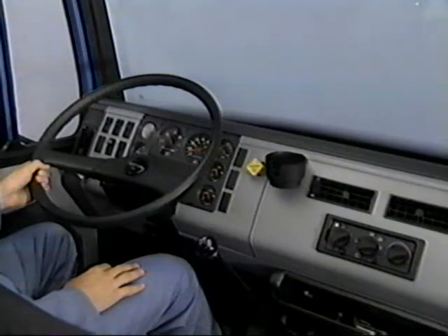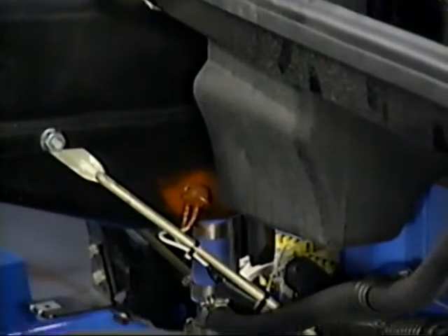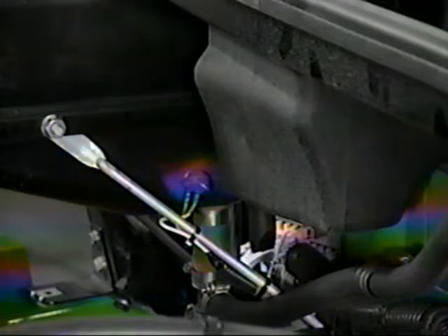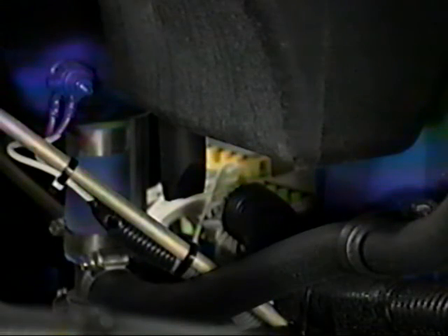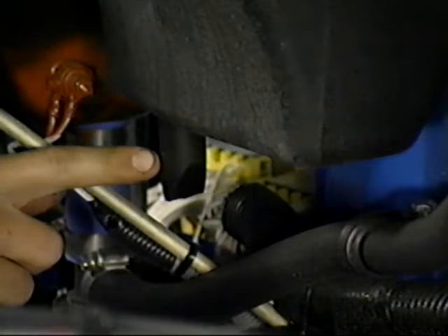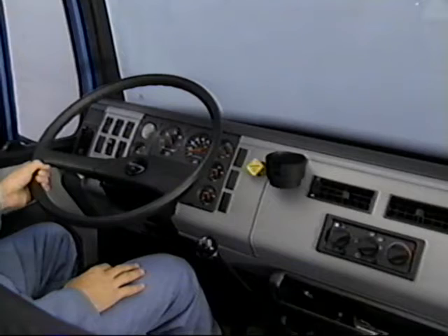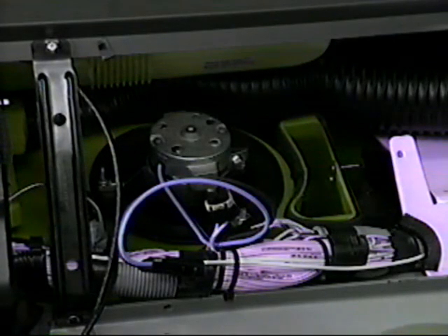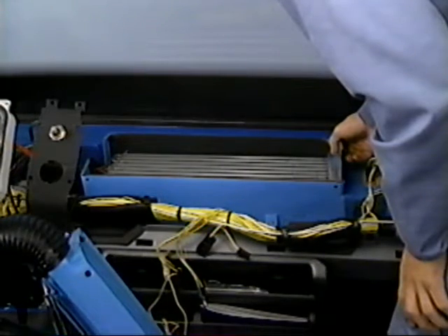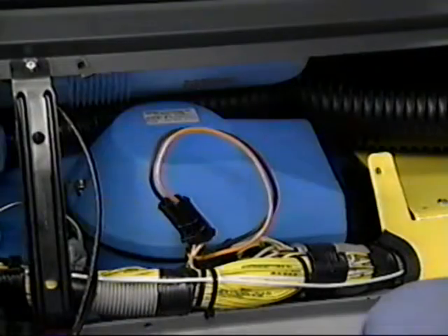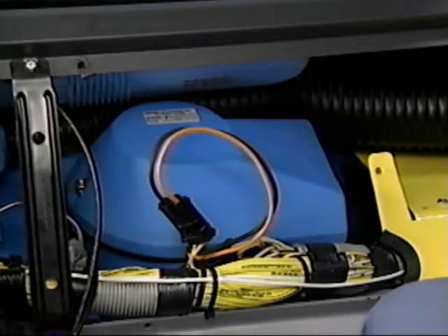The heater AC unit is mounted in the cab under the center dash panel. Fresh air enters the system through the fresh air inlet plenum, located on the right side of the cowl top. An evacuator valve at the bottom of the plenum expels most moisture from the air before it can enter the system. As air enters the system, it's pushed by a single blower motor through the heater core and AC evaporator coil. Excess moisture that may enter the blower housing from the inlet plenum accumulates at the bottom of the housing and drains into a hose, then out through the cab deck.